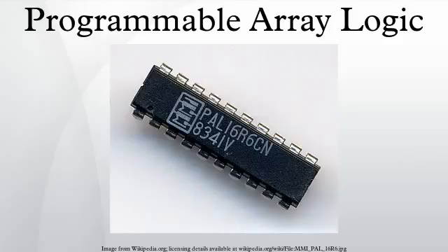PALs were used advantageously in many products, such as mini-computers, as documented in Tracy Kidder's best-selling book The Soul of a New Machine. PALs were not the first commercial programmable logic devices. Signetics had been selling its field programmable logic array since 1975. These devices were completely unfamiliar to most circuit designers and were perceived to be too difficult to use. The FPLA had a relatively slow maximum operating speed, was expensive, and had a poor reputation for testability. Another factor limiting the acceptance of the FPLA was the large package, a 600 mil wide 28-pin dual inline package.